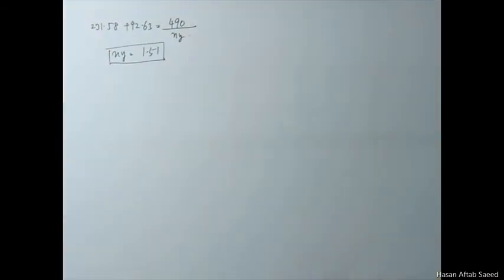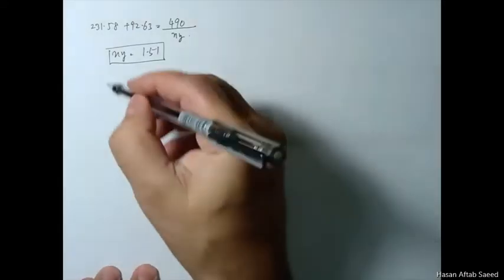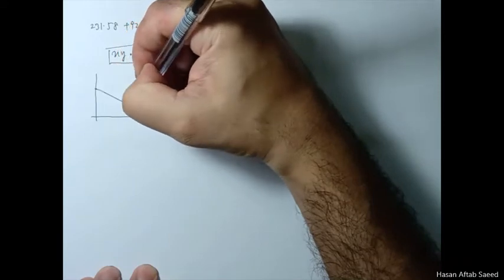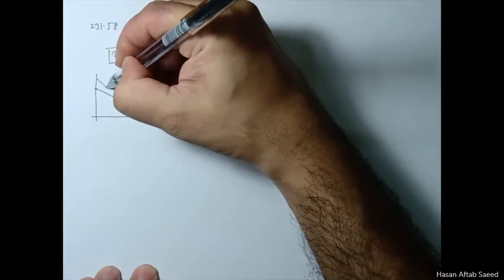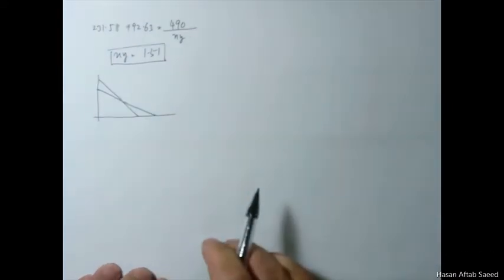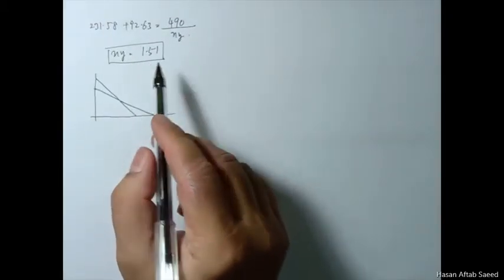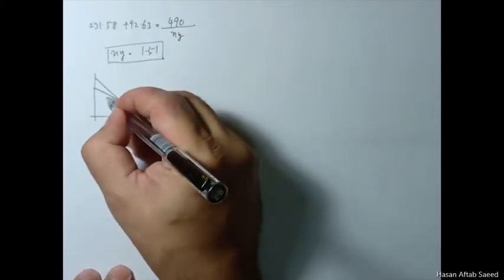It's good practice to check both, even if the question doesn't require you to. So if we talk about where this point plots, obviously we did it analytically, but graphically speaking, because your fatigue factor of safety is 1.2, whereas your yield factor of safety is 1.51, this is not plotting anywhere here. This is plotting somewhere around here.